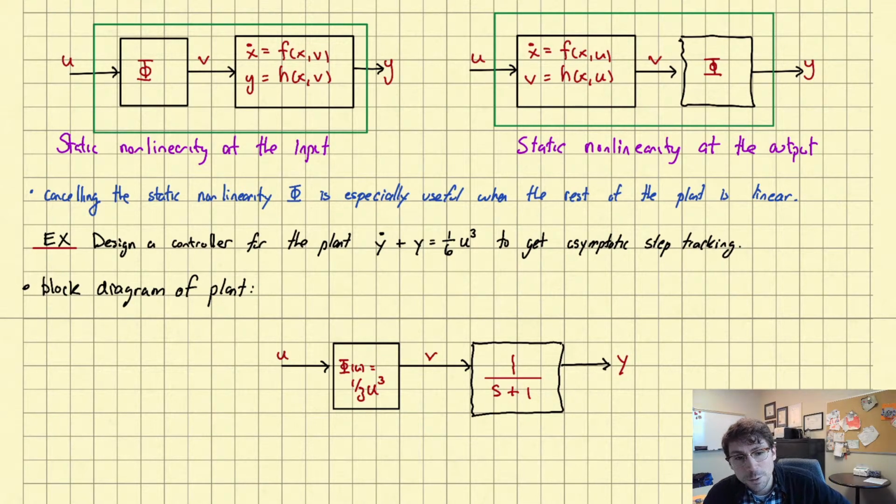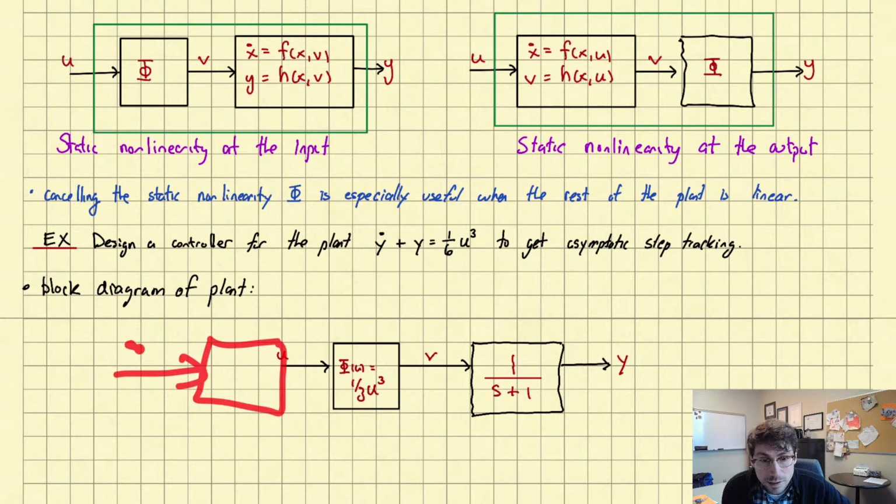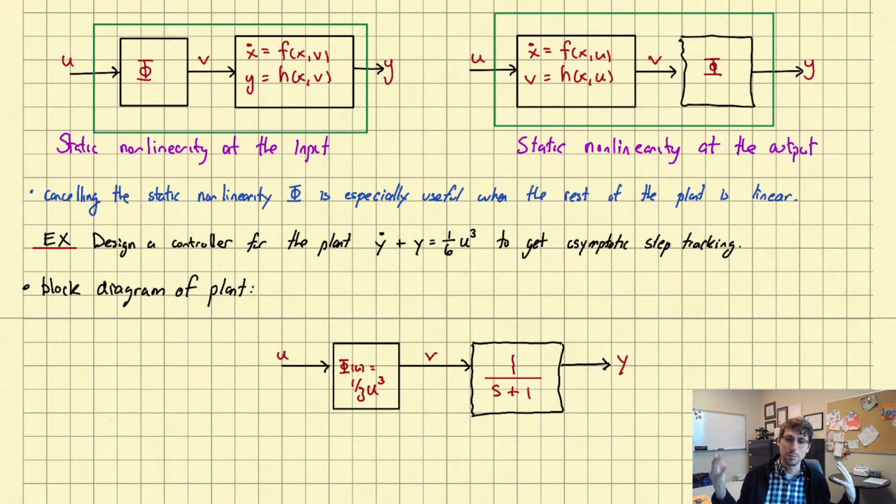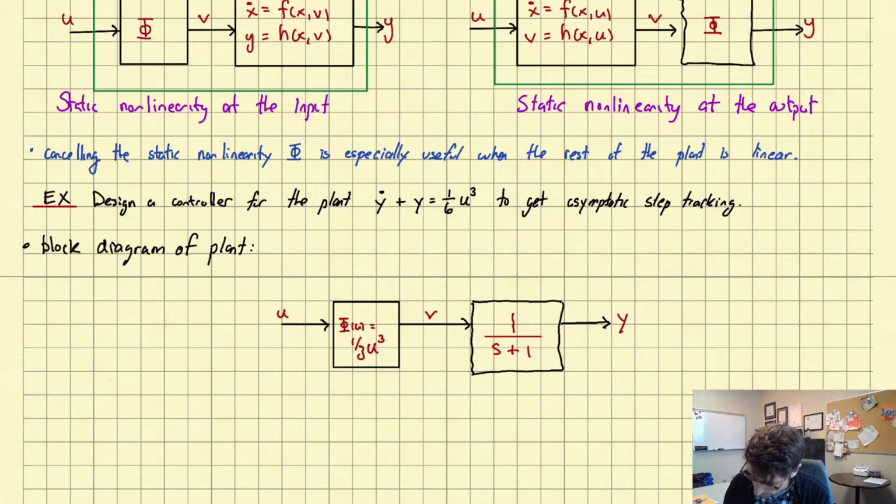Okay. So I guess you can figure out what you should do here, right? We get to pick this signal u, our control input. And so the idea is to cancel the effect of this guy by putting in a block here, which essentially does an inversion, cancels it out. And then, once we've added that block, we'll have a linear system from this signal, ideally, to this signal over here. That's the basic idea. It's very intuitive, what you would probably naturally want to do, but we're just trying to write it down a little more carefully.